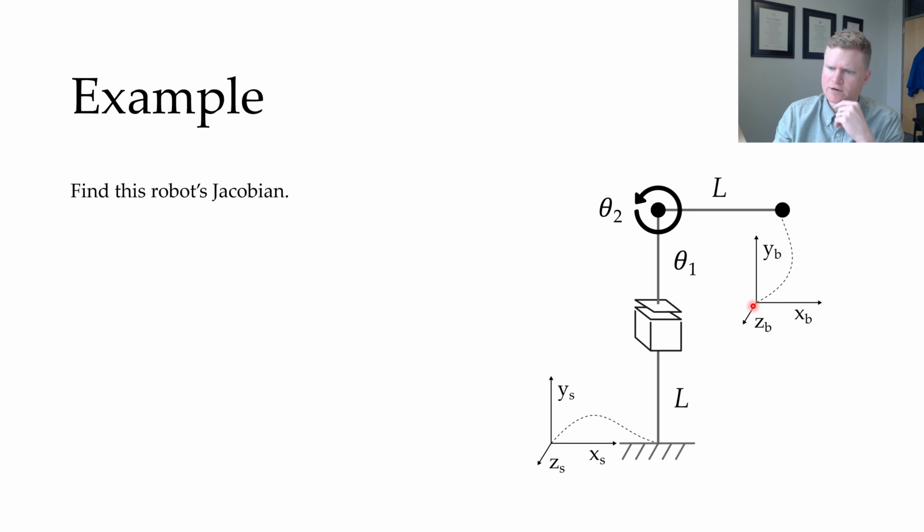All right, my second joint is going to be a revolute joint. The main thing is I need to find this omega s hat, and that's a unit vector pointing in the positive direction of the axis of rotation. So this thing is rotating counterclockwise positive.